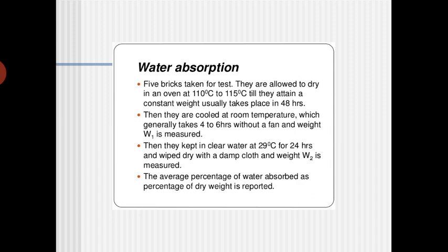Strictly speaking, we have to use distilled water, and all the bricks have to be immersed in it. Why distilled water? Because distilled water does not contain any ions. If any ions are in the water, they will be absorbed by the bricks. Then the property of the brick is going to change and it will affect the water absorption. So that is why he said clean water. Normally we will use distilled water.